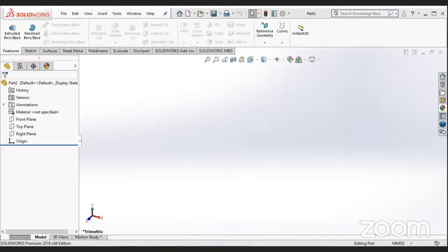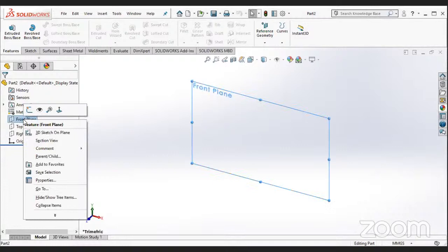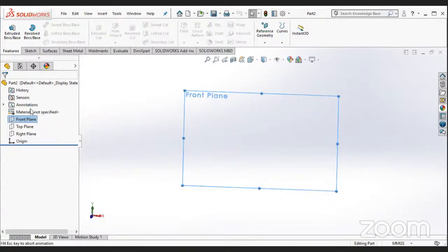So we can start it from a side view and extrude it. That will be the easiest way to approach this cap of a plumber block. So we first quickly make the center line in the origin and start making it. Again select a front plane, sketch on it.